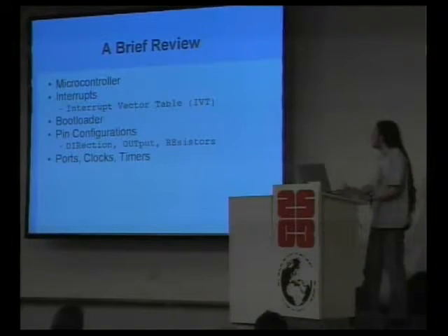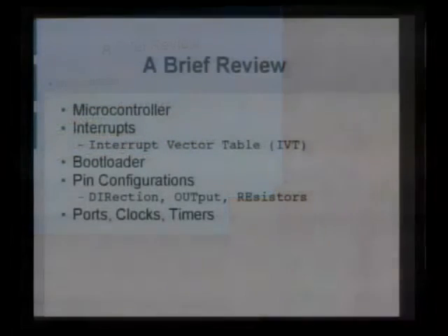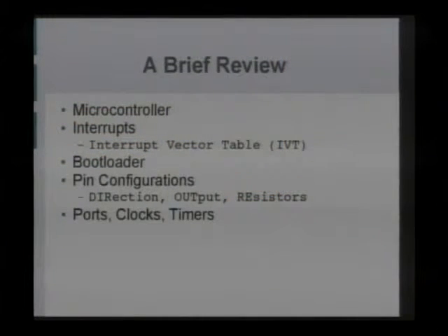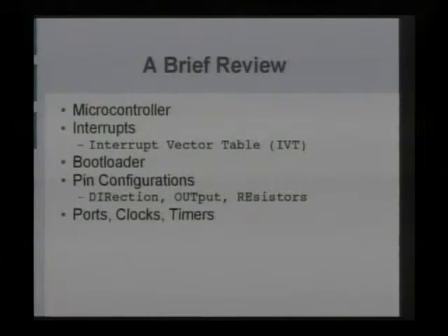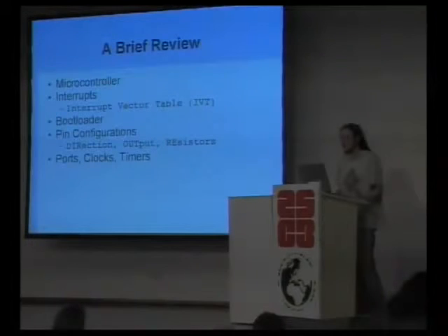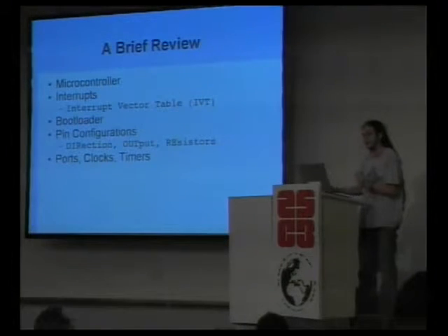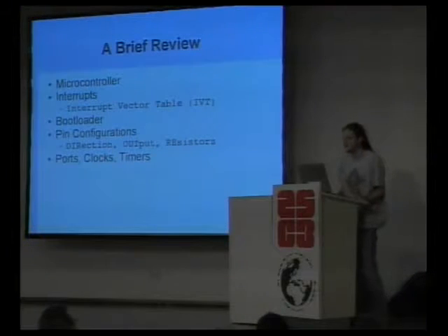So to quickly review, the MSP430 is a 16-bit microcontroller. It's von Neumann architecture, and it has a table of interrupts at the end. So wherever you have a callback from hardware or an event that's fired when, say, a pin rises or a byte comes in over a serial port, the microcontroller just looks at an address at the end of memory and pushes it into the program counter.